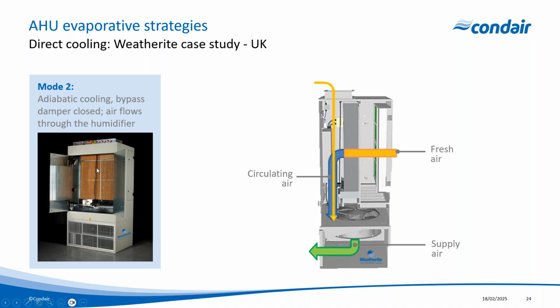Just a few points here on the evaporative system. So this is a recirculating evaporative system. So we do have a small sump inside the unit and then a small single pump there that's used to pump water to the top of the media. Any unevaporated water falls back into that sump and we'll continually recirculate that water, periodically draining some of that water out in order to maintain a specific water quality. And that really just helps to maximize water efficiency within the evaporative system itself. So as you can see, overall, a relatively simple system in terms of the design and the operation.